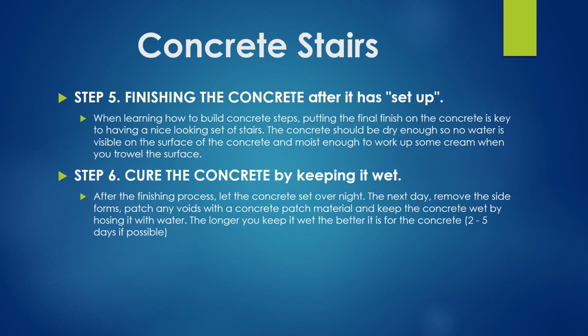When learning how to build concrete steps, putting the final finish on the concrete is key to having a nice looking set of stairs. The concrete should be dry enough so no water is visible on the surface of the concrete and moist enough to work up some cream when you trowel the surface.